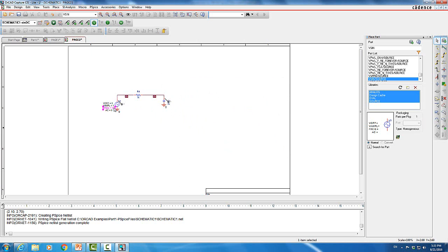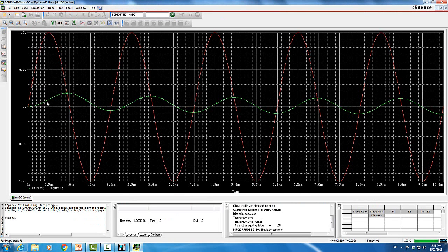The frequency is higher. We would expect that the voltage across the capacitor is going to be smaller because this is a low pass filter. So let's run the simulation, and when you do that, you can see that the voltage dropped by a big factor, roughly 20 dB, more or less. That works according to what we stated, that this is a low pass filter. You can even increase the frequency by a factor of 10 again, and you're going to see the voltage drop even more.